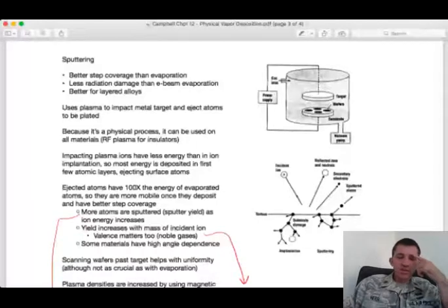I might be getting a little mixed up, but that's kind of beside the point, right? A changing current produces a changing magnetic field, which induces an EMF, an electromotive force that pushes these electrons around, and they meet resistance in the material, and so you can heat a crucible in a similar way that you would heat a wire, by moving those electrons around and producing Joule heating. However, if I heat up a crucible really hot, right, I'm going to lose some of those atoms.